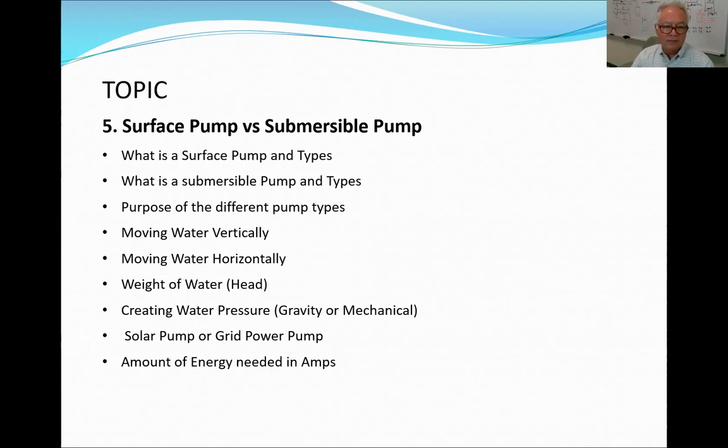What's the purpose of the different pump types? Here again, it's how far down are we pumping? How much water do we need, in gallons per minute? And are we going to be going horizontal, or are we going to be going vertical? Moving water vertically, you need a pretty heavy duty pump, one that can push water straight up out of the ground because water weighs a lot. And moving water horizontally, here again, we talked about those different types of pumps.